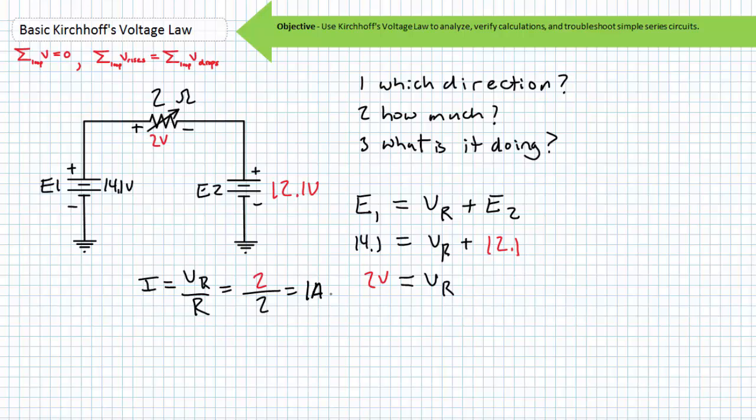As the second battery's voltage increases, the voltage differential across the adjustable resistor drops and drops, and we can progressively open up the tap wider and wider by decreasing the adjustable resistor to allow that continual 1 amp of current into the device. Finally, the device will charge up to 14.1 volts. At this point, current flow will cease to be exchanged between the sources because there is no voltage differential. With 14.1 volts on one side of the adjustable resistor and 14.1 volts on the other, there is no differential and no current will flow.